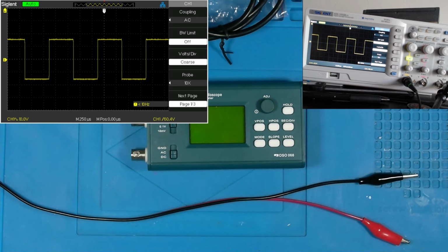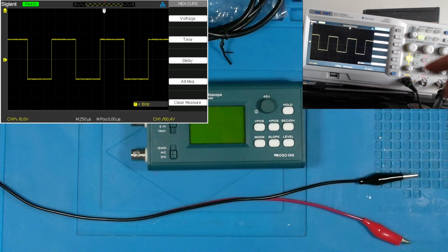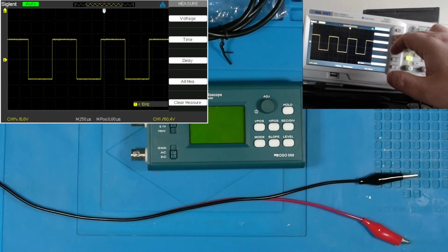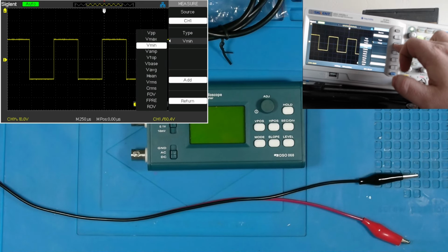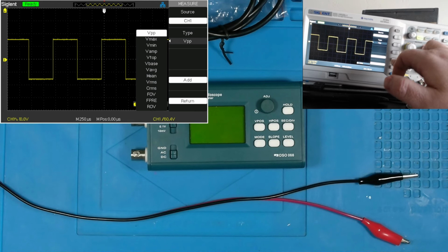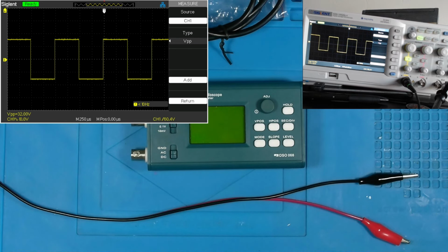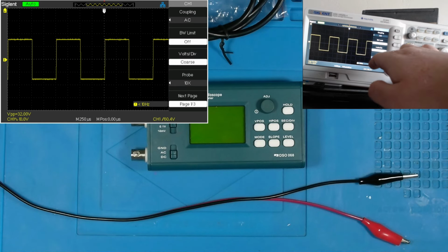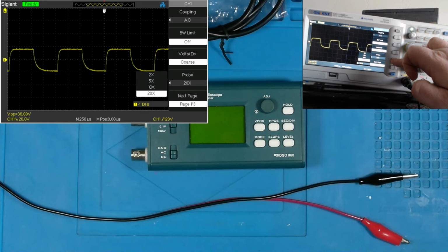All right, pretty easy. Also want to show you something else here real quick. Again, the oscilloscope has a measurement function. So let's go to voltage. Instead of Vmax, we're going to set it to volts peak to peak. And then I'm going to add. Now on the bottom left hand corner, you'll see that 32 volts peak to peak popped up. But I'm still in 10 by, even though I set this to 1 by. So let's change this to 1 by.